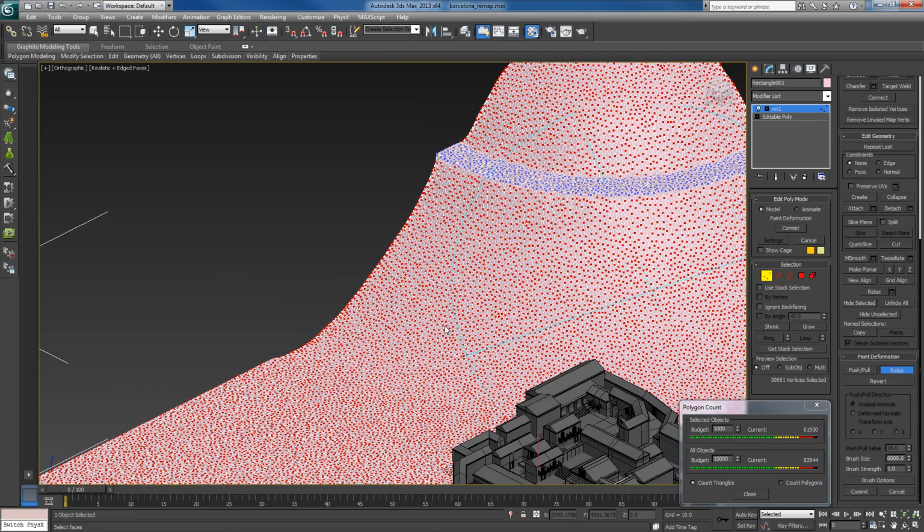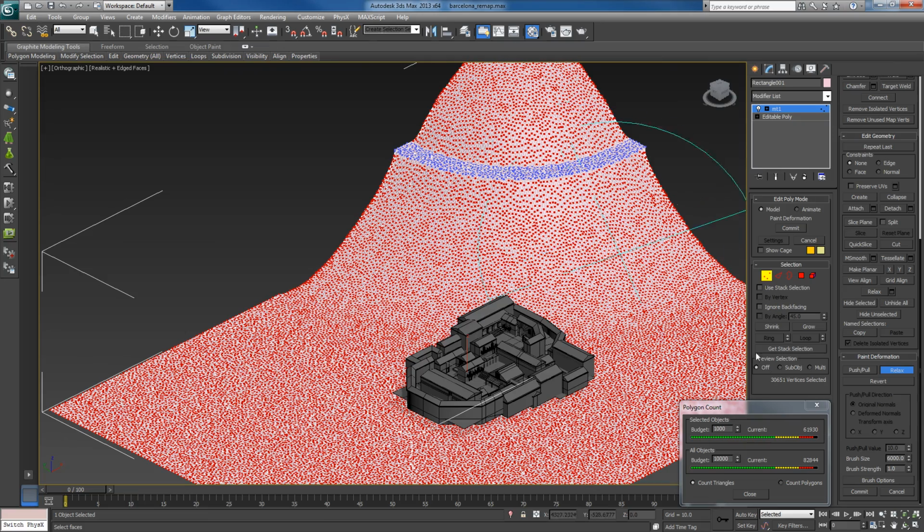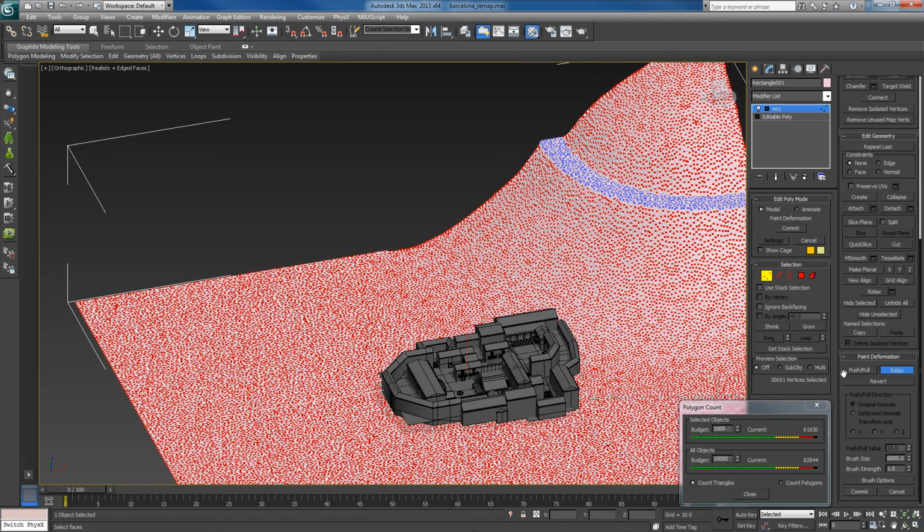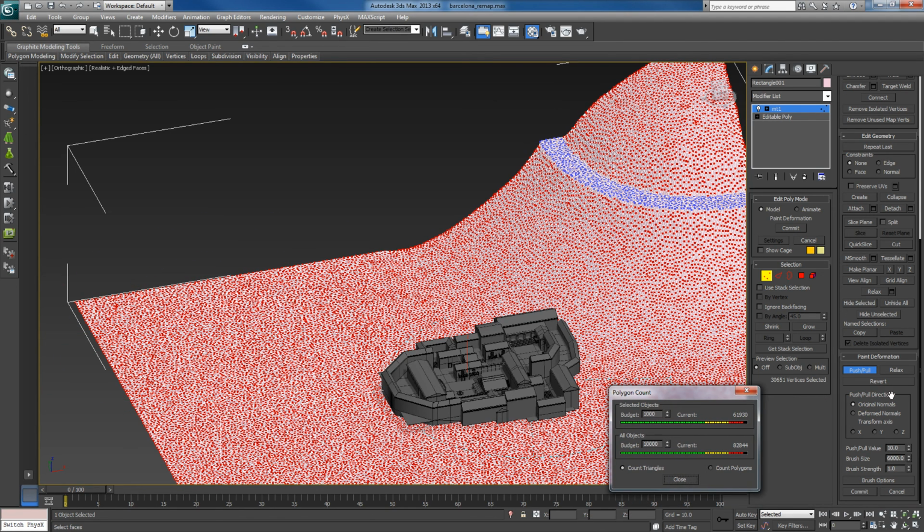I'll call that idea, the need for a relax, consistently rather important. Now this is something that I consistently do. Edit, relax, edit, relax, edit, relax. I'm not going to be doing this obviously in this video because it would consume an amount of time, but the result is that the UV mapping usually takes care of itself pretty good, and it actually allows us to extract the low resolution model out of this much easier, which puts us into our next section as to tools,